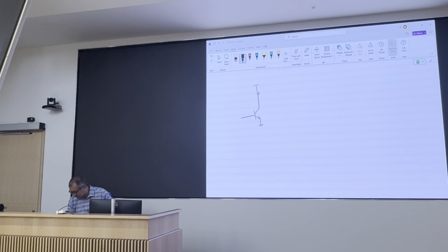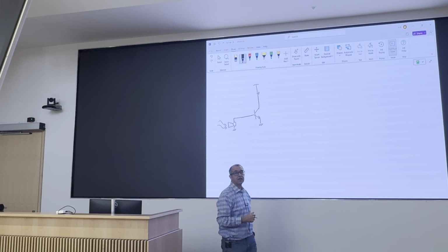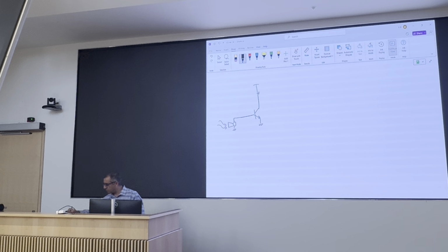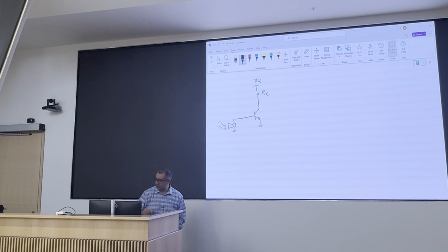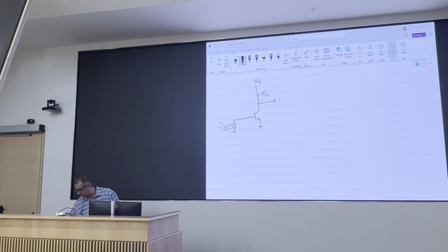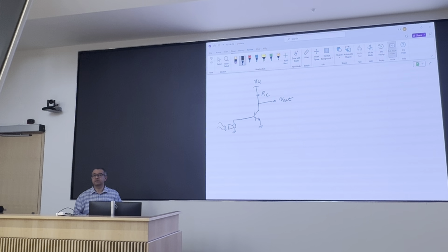So let's say I did that, and I made this circuit. Let's say this is the speaker, but it's the speaker that I'm using as a signal source. I'm speaking to the speaker. And let's say I have enough power supply here, and I've chosen the right RC to give me enough gain. My goal is to amplify the signal from that speaker, because I'm going to get millivolts, and I want to amplify that. Will this circuit work?